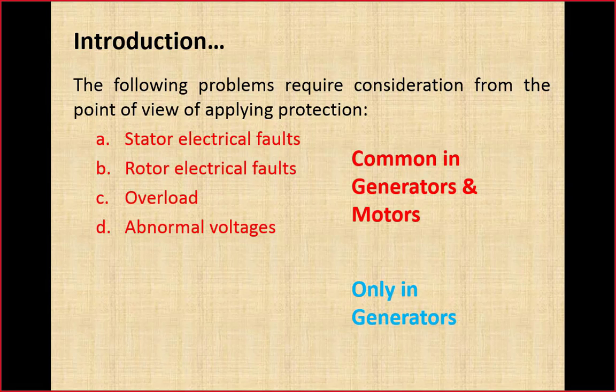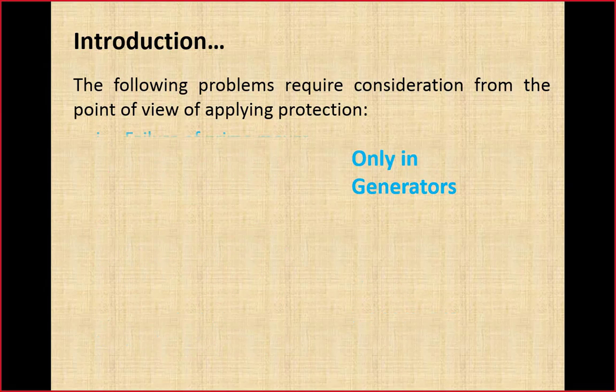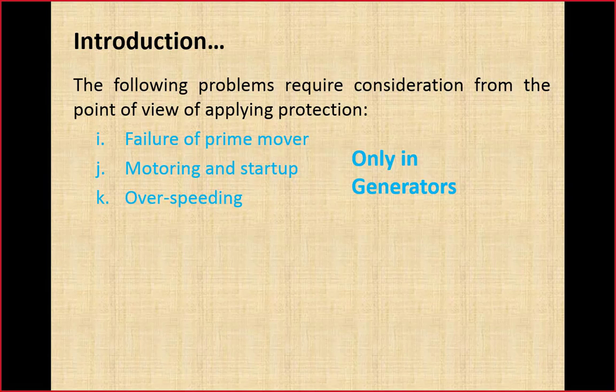And here these problems are only associated with the generators. For example, abnormal frequencies, it has nothing to do with the motors. Such problems are only associated with the generators. Unbalanced loading, overfluxing, inadvertent energization, by mistake energization of generator, failure of prime mover, motoring and startup issue, overspeeding.